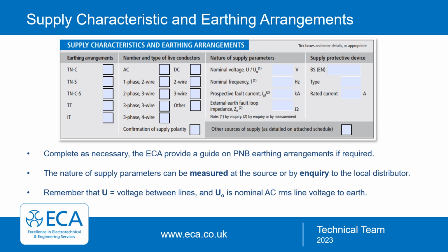When undertaking the nature of supply parameters, it should be a consideration to inquire to the local distributor for the earthing arrangement and also supply parameters to minimise any exposure to live working, so they can be measured or they can be sourced by inquiry.